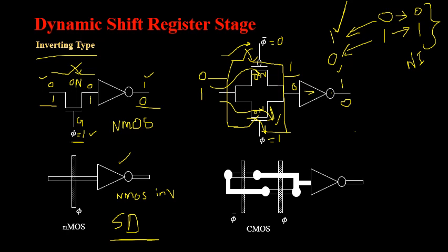So now how to draw the stick diagram for this particular case. P MOSFET and N MOSFET are connected in parallel, that is transmission gate logic. So I have to consider two layers. Two transistors are present, which means two polysilicon layers I will consider like this. So hope this is understood.